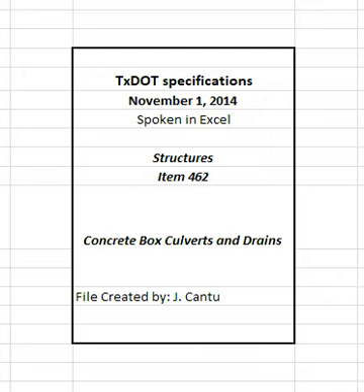2.3 Testing. 2.3.1 Cast in place. Provide test specimens that meet Item 421, hydraulic cement concrete. 2.3.2 Formed precast. Make, cure, and test compressive test specimens in accordance with Tex-704-I. 2.3.3 Machine-made precast.